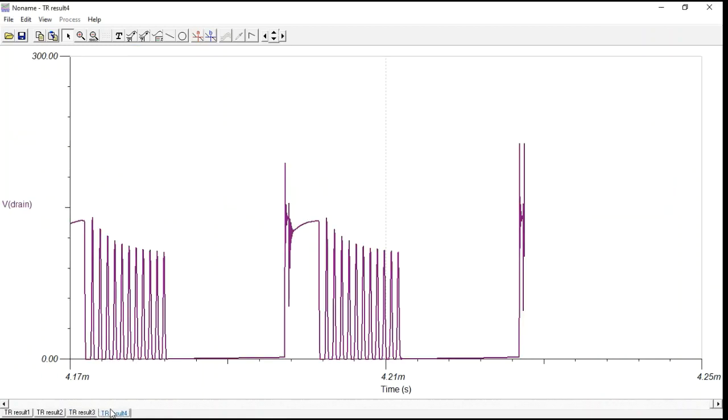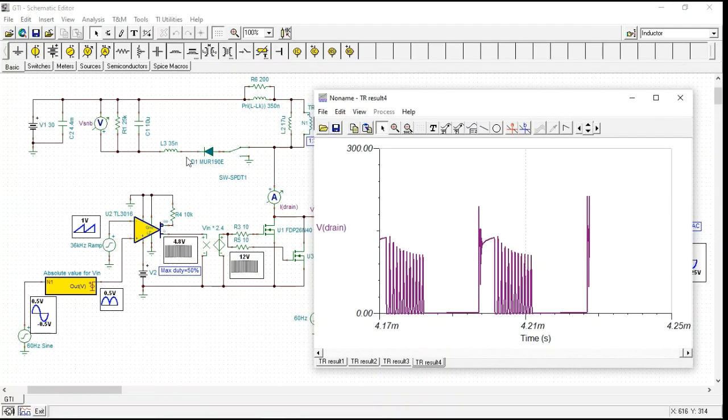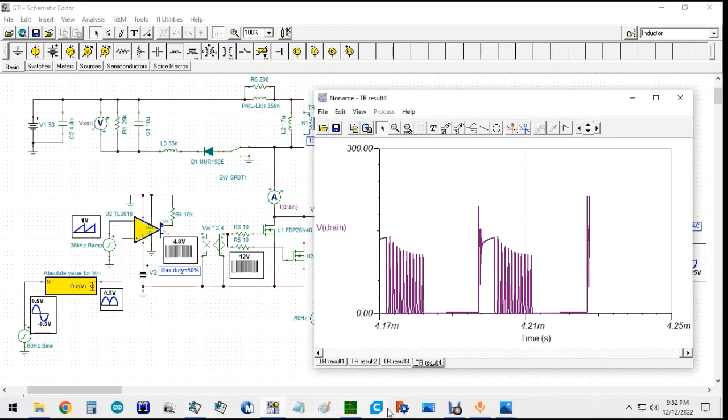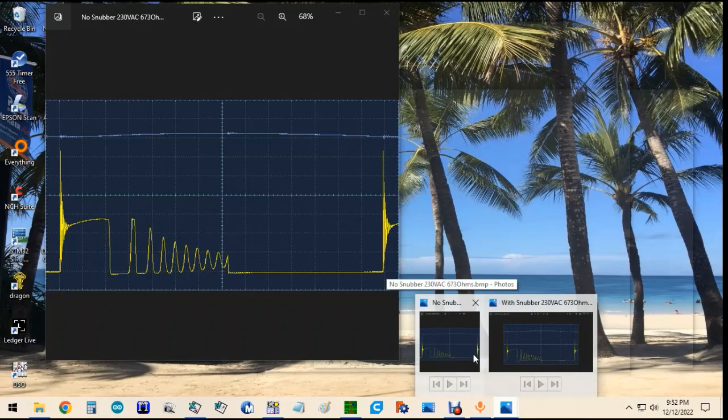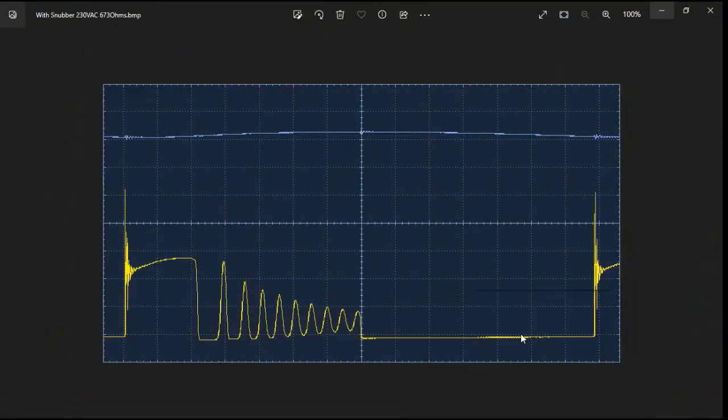But if you put a real world snubber in, the way to overcome this now would be to say, okay, if this is true, which it is, because I can see what's going on in the real world with the snubber. I'm still getting this, right? And in fact, now it's 51, 52, 50. This is probably very close now to the same. So 35 nanohenries might be very, very close to what I actually have in series inductance.